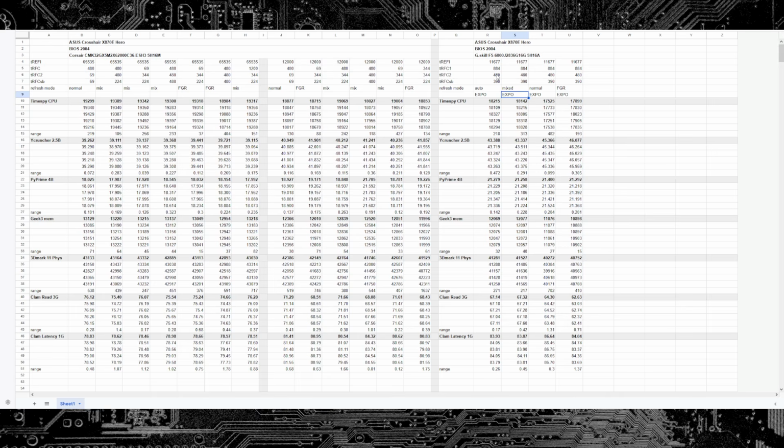It doesn't specifically bias towards bandwidth or latency. It's kind of misusing the memory timings, right? Within my understanding of the JEDEC spec, switching which refresh mode DDR5 is in on the fly is entirely supported by the spec. But within my understanding of the spec, you should probably be using TRFC1 when you're in normal mode, and it just doesn't.